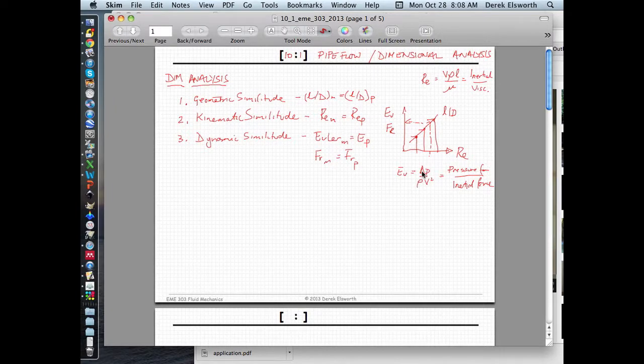And so the beauty of this was that if we could just guess or have some intuition as to what the properties were that would affect the performance of our system, density of the fluid, viscosity of the fluid, the geometry of the wing, the pressures acting on it, the speed the fluid is flowing past it, we could come up with some relationships just by experimentation, by using the so-called dimensional analysis, which is really dimensionless analysis, because all these parameters have no dimensions, and we could come up with some design values. So it's an incredibly powerful method, which will also apply to pipe flow. And so we thought about it in those veins.